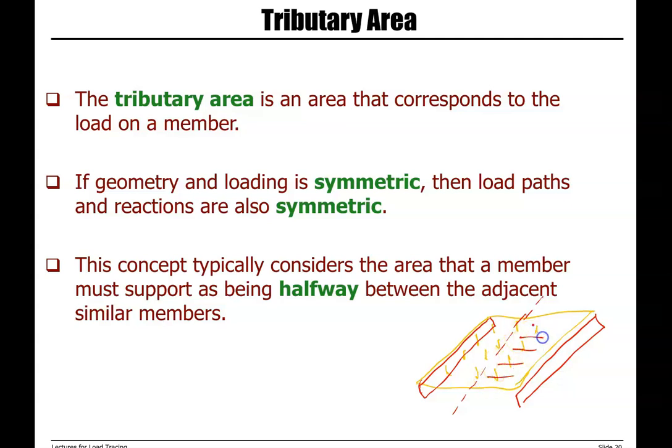This area is called tributary area, and when we have a symmetric system, it's halfway between the adjacent similar members. The adjacent similar members here are the two beams that we have, and tributary area is halfway between these two beams.